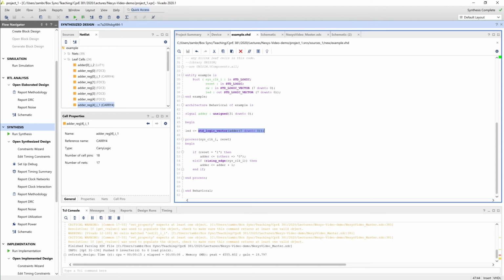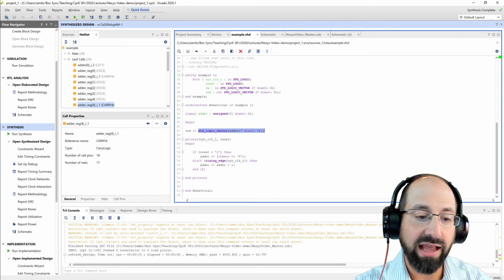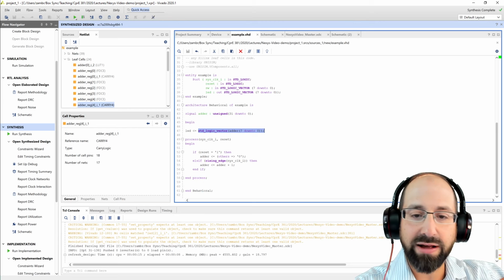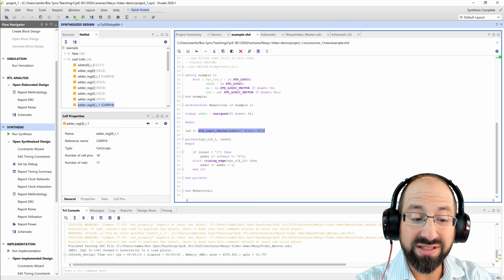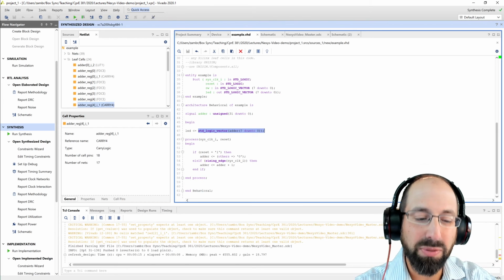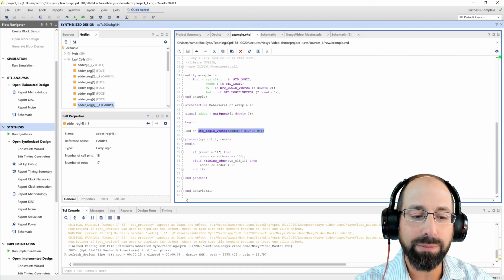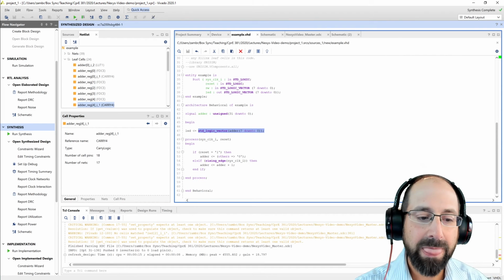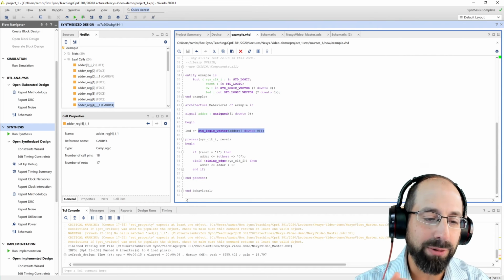That allows our design from the VHDL perspective, as long as we're aware that it's happening, to be very clean and straightforward and simple. And if we already built a 32-bit circuit that we like, let the tools optimize the stuff out that we're not using. So for example, in your processor project part B, where you have to calculate PC equals PC plus 4, you may be tempted to create a separate plus 4 circuit, but you don't need to.